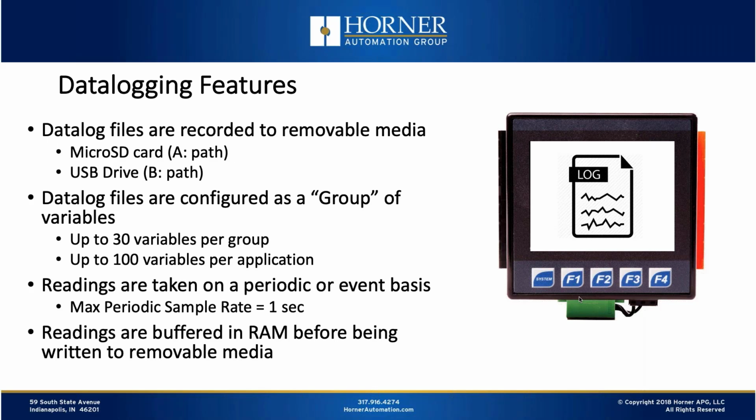Now, in terms of data logging features, the data log files in the Horner OCS all-in-one controllers are recorded to removable media. You have your choice between using the microSD card that you can plug into the built-in slot, which is the default path for data log files to be created. You don't have to specify a path, but if you do, that would be considered the A drive on an OCS controller. If you prefer to log to USB instead, you can specify the B drive under the path, and then it's going to log to USB.